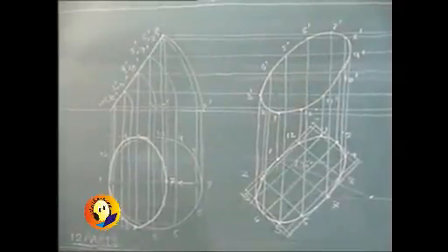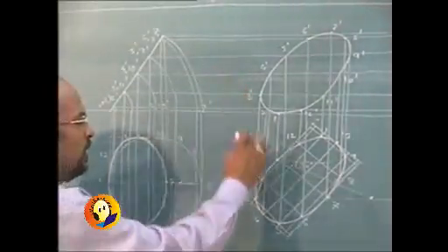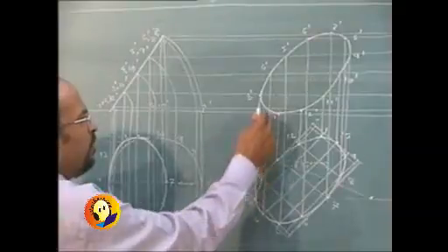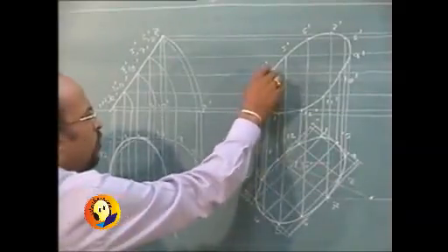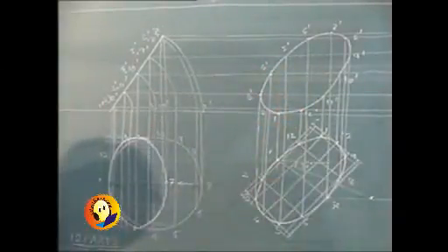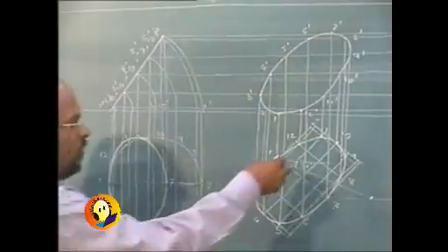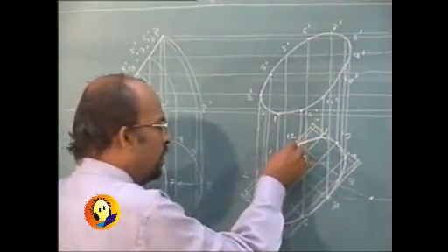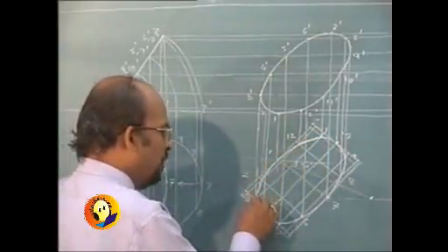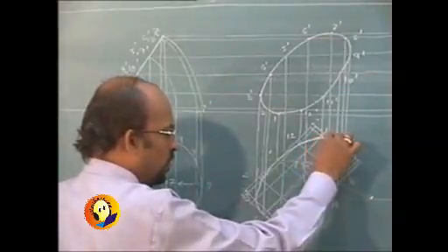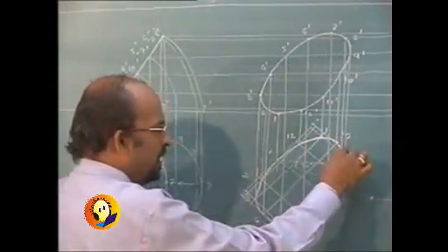And also observe that I am not arbitrarily drawing the projectors. I am taking every projector only up to the respective path, and the paths might be extended. Only the final two ellipses should be drawn dark. Everything else is a construction, should be kept as light as possible.